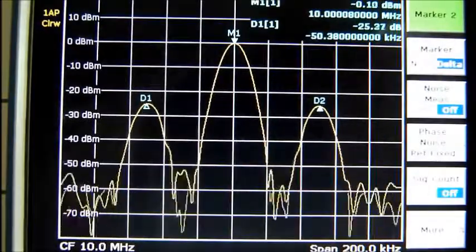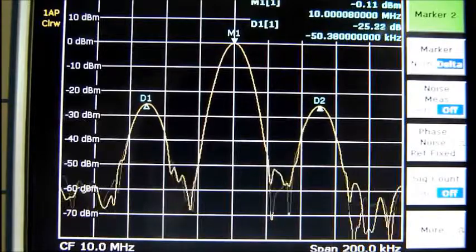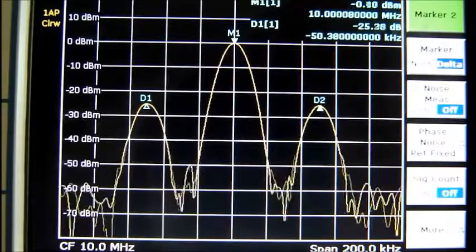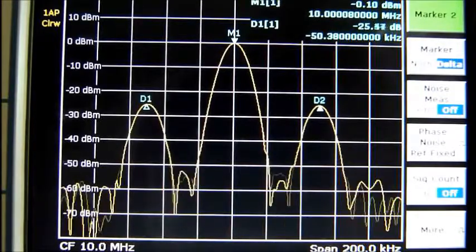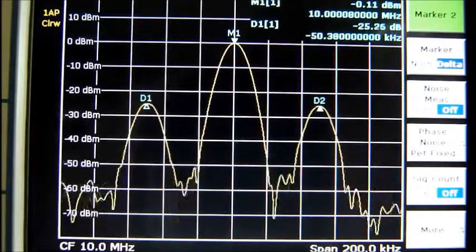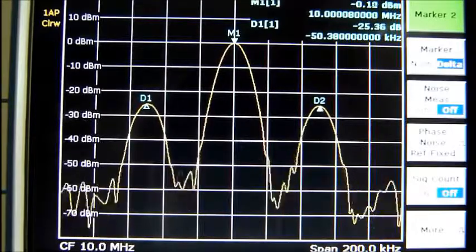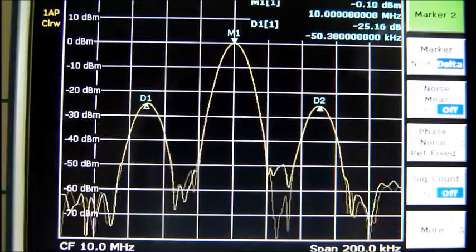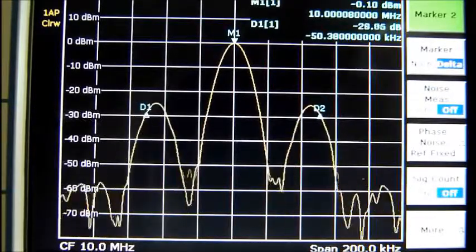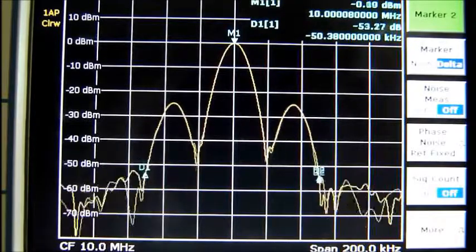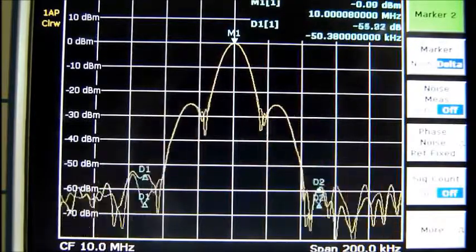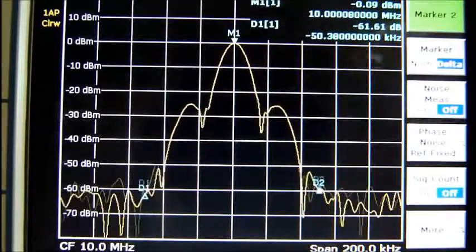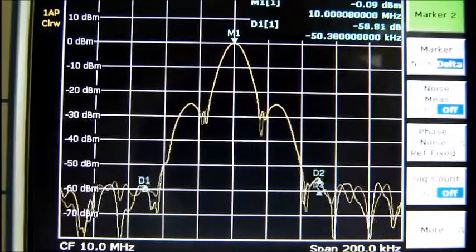For this particular signal generator, the information signal or the sine wave that we are using as a modulating signal has a maximum frequency of 50 kHz, which is the one that we have just selected. So the only thing we can do is decreasing that frequency, but that is enough to demonstrate the concept that when we decrease that frequency, we can see how those sidebands get closer and closer to the carrier frequency because the frequency of our information sinusoid has been decreased.